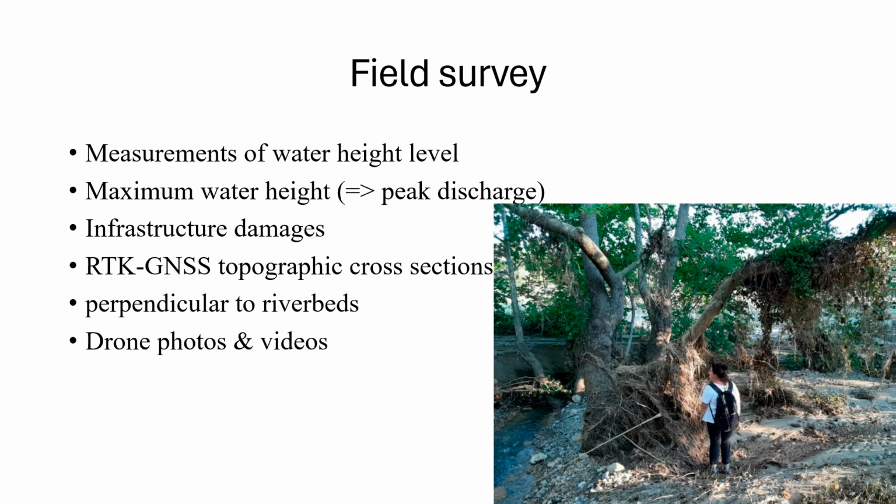Documentation of damages using a commercial UAV. Flight elevation ranged between 50 to 70 meters for detailed photos and 90 to 110 meters for panoramic views. The route of the flights was planned in a way so that the areas of interest could be captured and a sufficient number, 80, of photographic and video material could be obtained so that the flood limit and the impacts of the event could be determined.